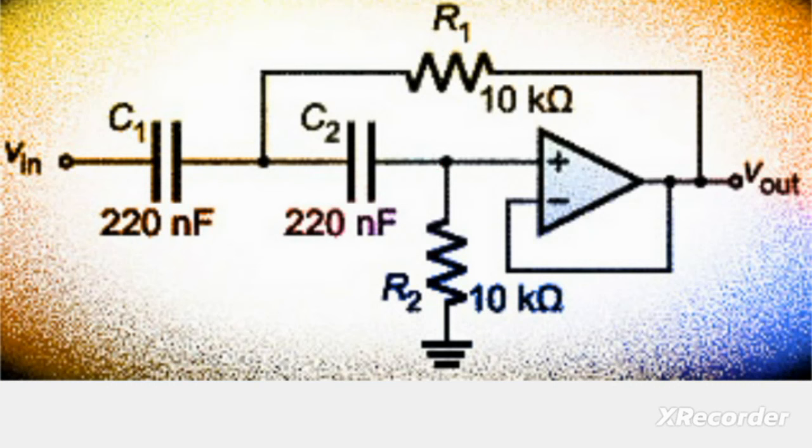Now this voltage follower property with extremely high input impedance and extremely low output impedance comes due to the advantage of a very high open loop gain of the op-amp that can be indicated by a letter A right over here.